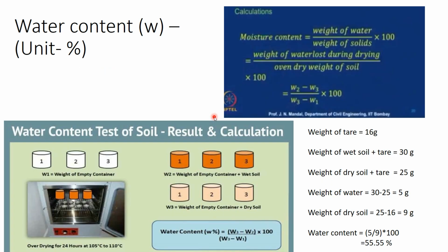So the first thing we are going to find out is the water content of soil. Imagine we have brought a gunny bag of soil. Usually 3 to 4 gunny bags come for consultancies. They will bring the soil to the lab and do the soil processing, which you can go through in the video. But on a lighter note, there is some raw soil brought from the field, and the soil will be spread out for air drying for 24 hours.